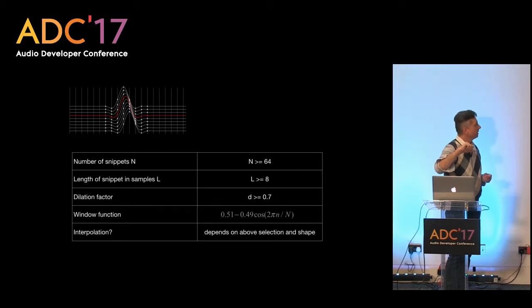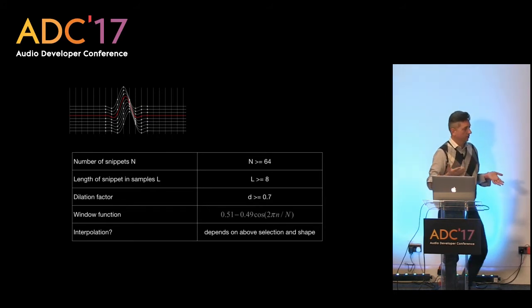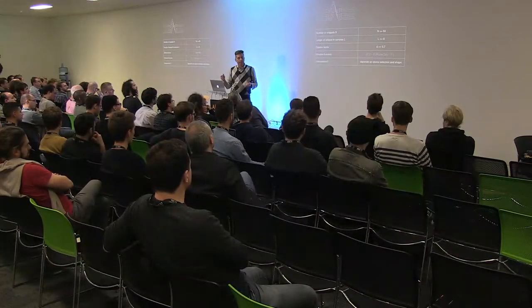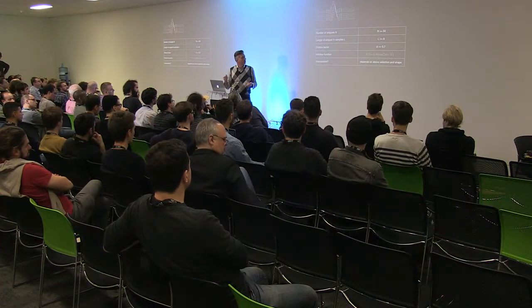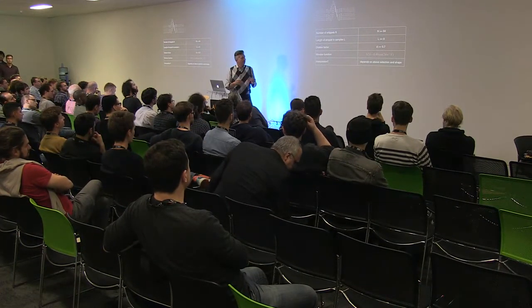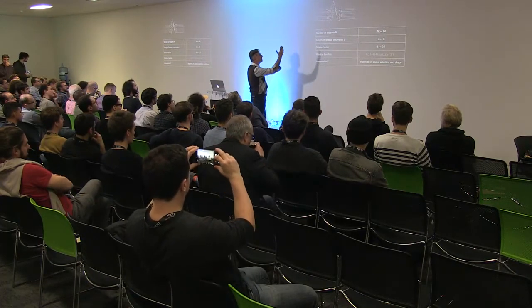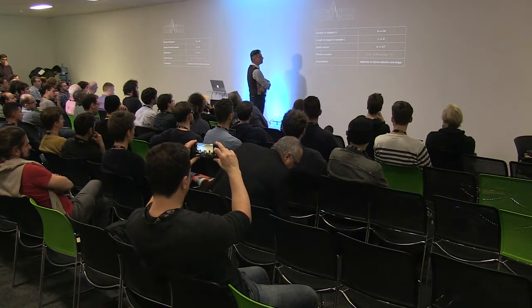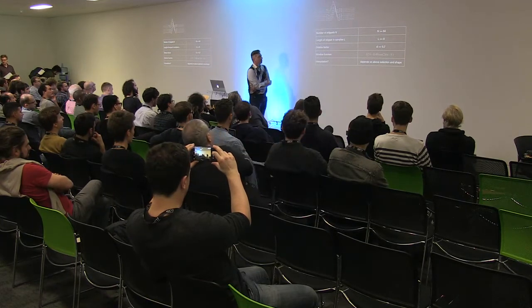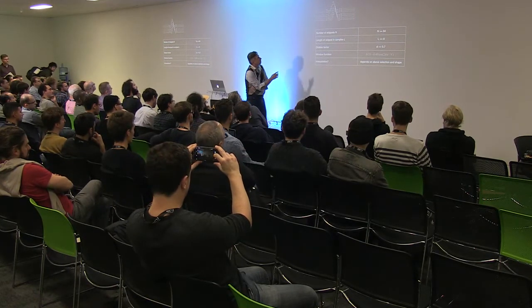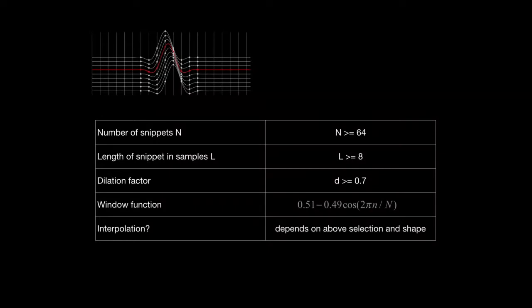You get a triangular wave if you chain two integrators, like an integrated square wave becomes a triangular wave. But this is even more sensitive to slight errors in DC, and slight errors in time will also show there. So if you do triangular waves, I suggest you interpolate in between those.